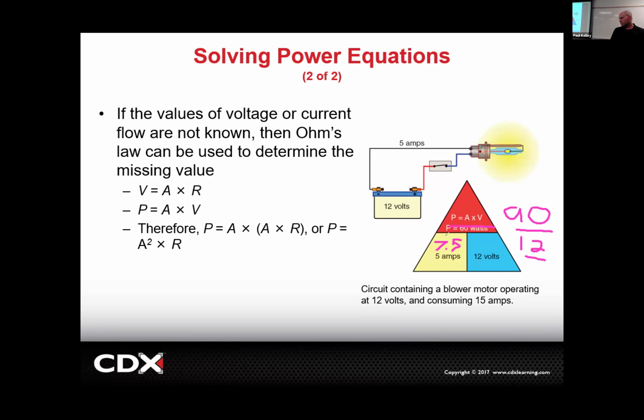So heating creates more resistance, or at least both go together, right? And so if we were trying to pull 5 amps and there was just a little bit of a loose connection at the bulb, that's going to make some heat. But the more amps you're trying to flow, the more heat there's going to be because it's going to become more and more resistance.